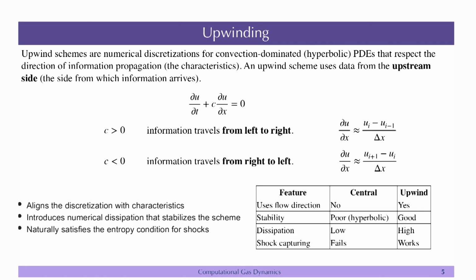So this is what we saw: when we use upwinding, it respects the flow direction, the direction of the information flow, and that is why upwinding works, but central differencing does not work in the convection cases, basically the hyperbolic cases. And lambda, given by C delta t by del x, was stable for less than 1, that is what we saw in the last class.